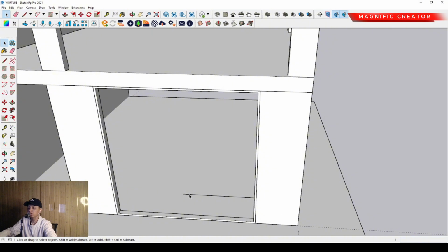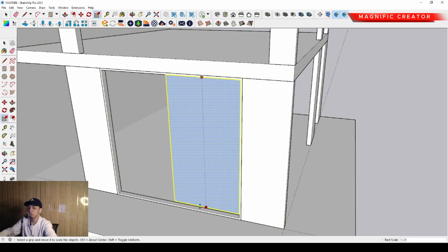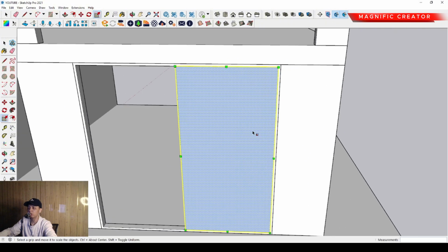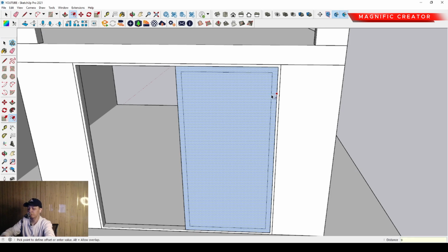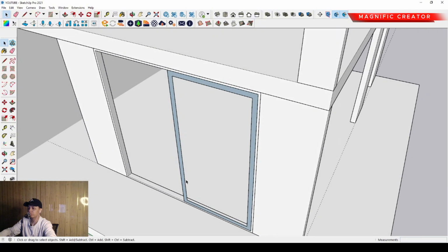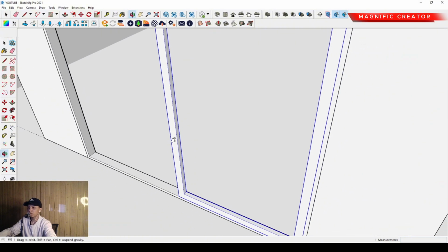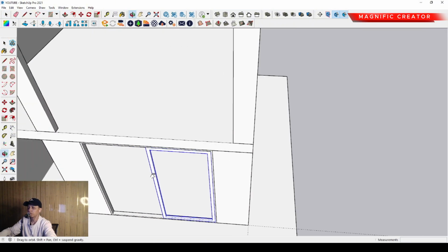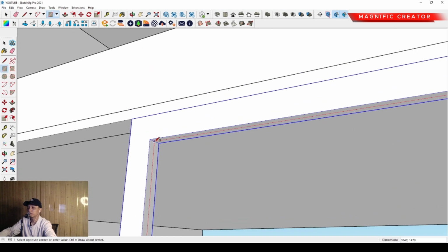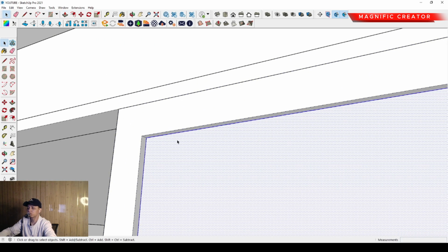We are attempting to make a large transparent door to provide enough daylighting in the indoor area. Then we offset it inside for this frame. We can use 90 millimeters for the frame thickness. Then we push it to the back around 30, or maybe about 50 millimeters, for the thickness. Then we can make the glazing, push it to the front, and make it a group.